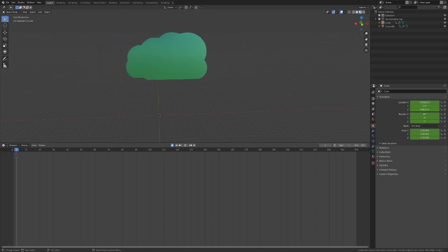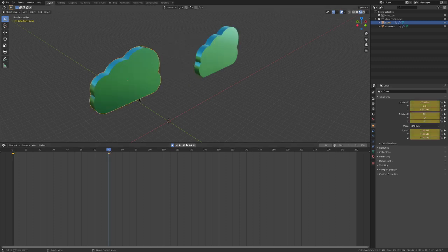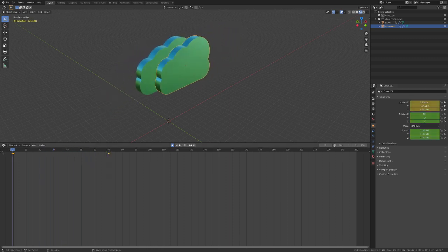If I want to animate also the rotation, I would do exactly the same thing. So I would go to each single object, I would add a keyframe in the rotation, add the keyframe in the rotation, then I move to the same keyframe here, and I will rotate again while this is activated. So it's not this one. You can clearly see the movement now.